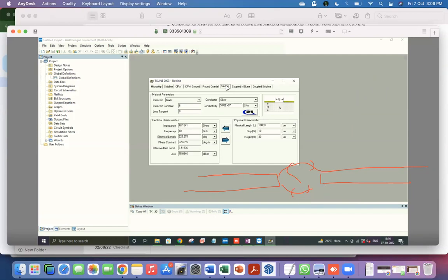This has an indirect consequence on understanding of the CPW mode. So that's why I'm discussing this here. And again, the only relevant dimension here is basically the gap between the metal and the height of this substrate, right? This particular height here. Why does that matter? It's again the same idea of how much the field lines are going to penetrate.